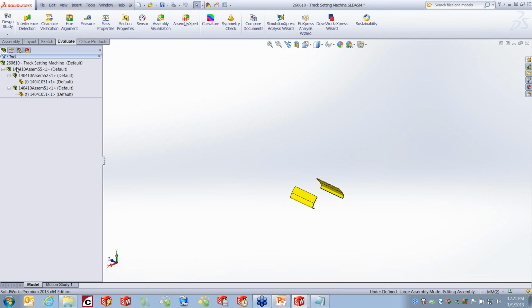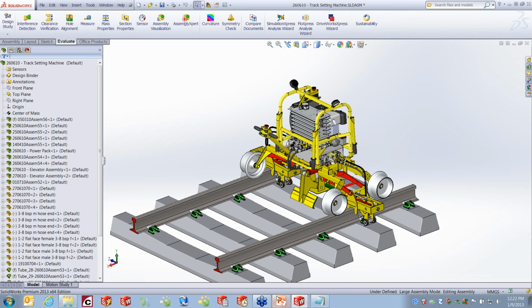If you know what type of information you're storing on the files, you can use it inside your assemblies to start to analyze and take a look at what you want to show and filter within that tree. And it's very easy to get back. You just delete what you've typed in. This will go ahead and reset your graphics area with all the components.